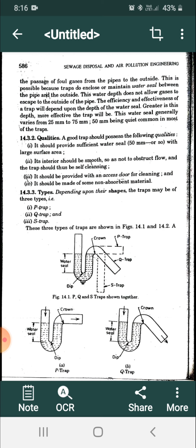This is called a water seal. So once the waste goes outside through flush out, what happens? See, it will join the pipeline. Suppose in apartments, with a number of floors, other pipes also give joint. That is a connection to the same pipeline. All the waste will go through the single pipe.